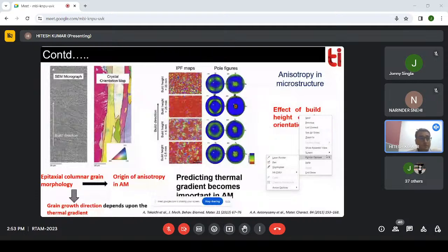If you see, these are the plastic strains or residual strains which are observed. If the material were homogeneous or fully recrystallized, it should show a single grain color. Let's suppose a particular grain orientation, 111 or 100; it should be in a single color. But now you can see there are some strains available in the material.